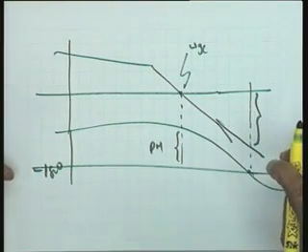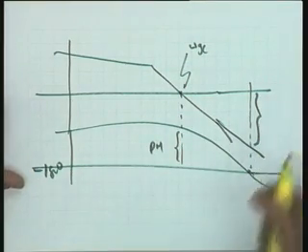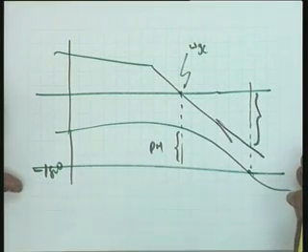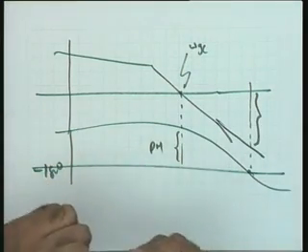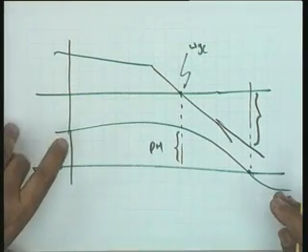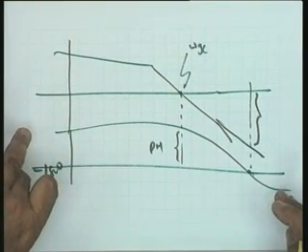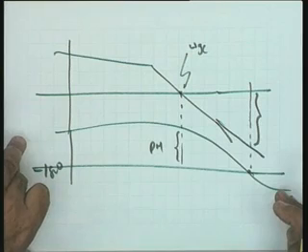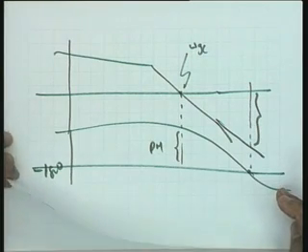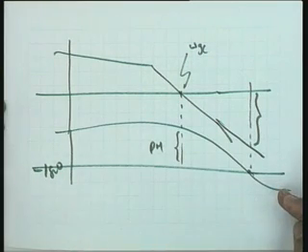This much of margin is available before the system becomes unstable, and hence this is a sketch of a stable closed loop system. An important point to note that from open loop frequency response characteristics, you are able to obtain the characteristics of the closed loop system, and these are important indices for design as well. Particularly the phase margin is a very important index.